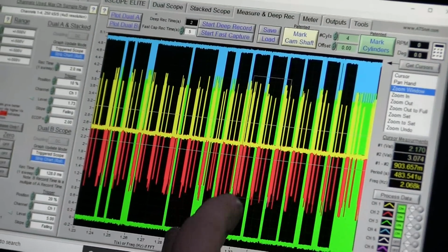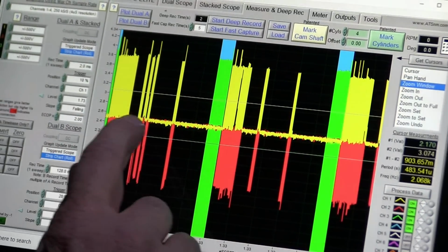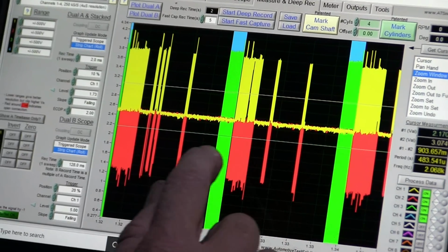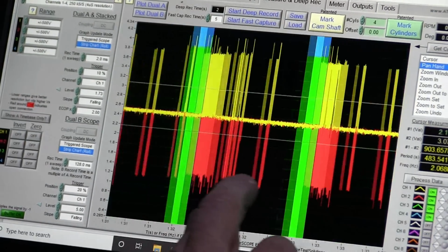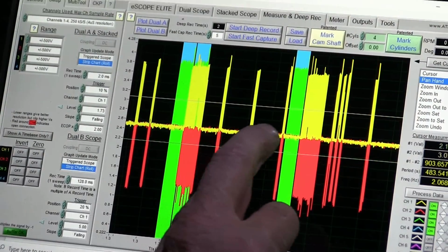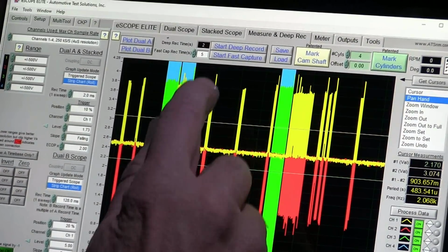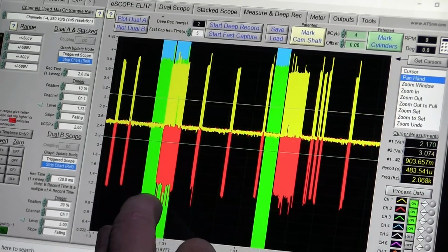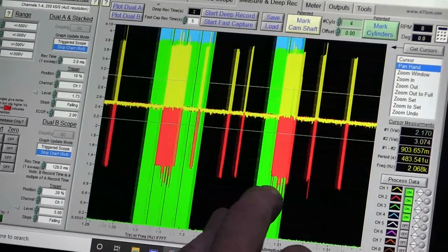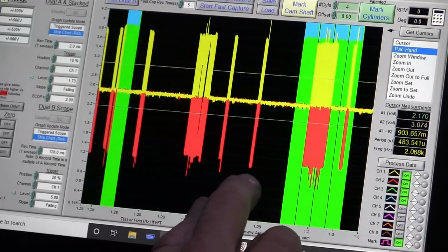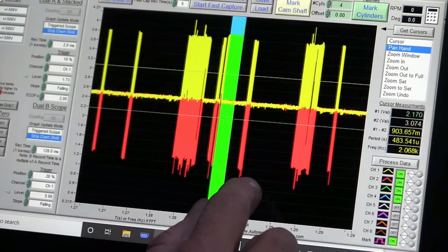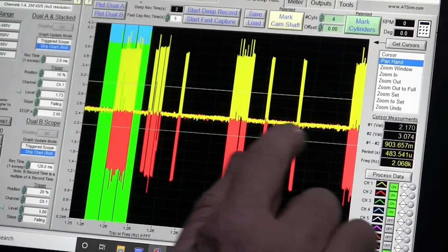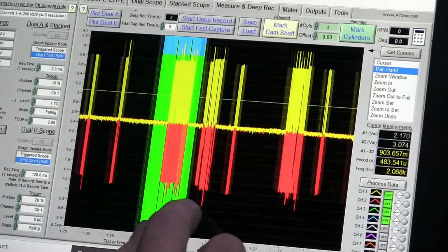So now we can see by unplugging that connector that we now have CAN and we have communication packets that are going on here. And so what we've got is we can clearly see we're at 2.5 on the bias, and we have the rising and the falling. And again, this is a voltage differential scheme, and again, this is to limit the radiation effect out of the wiring. So that's really what's going on here, and we're good to go here. So now we know that the bus is back up and operational.